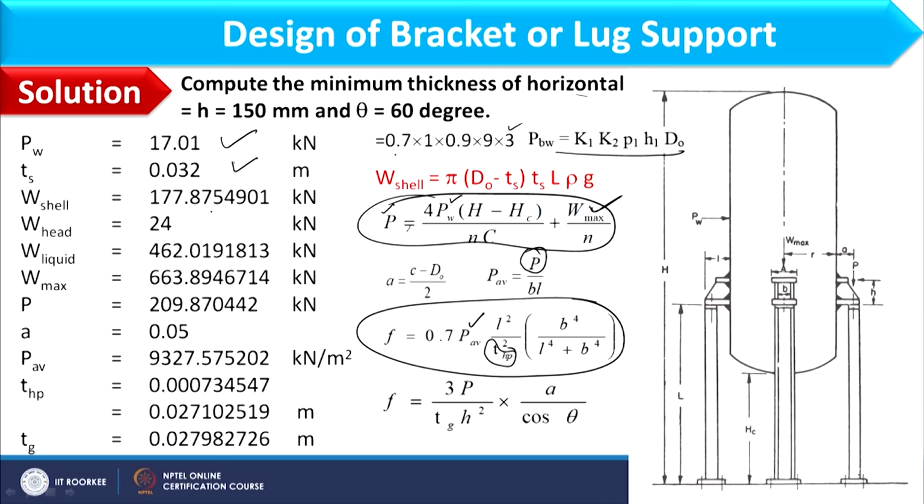However, for maximum weight we consider the maximum possible situation, and that could be when the vessel is completely filled with the liquid. Okay. So, here we will consider weight of shell, weight of head plus weight of liquid when it is completely filled in the vessel. So, to compute this, first of all we have to find out the weight of shell.